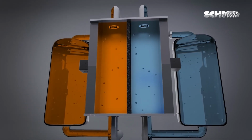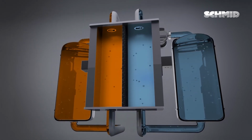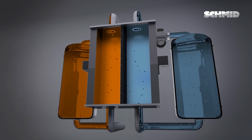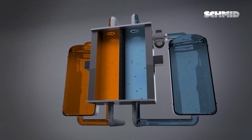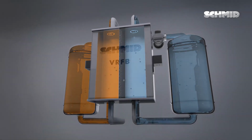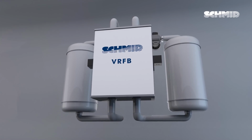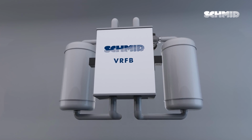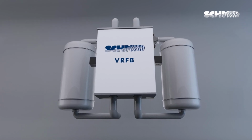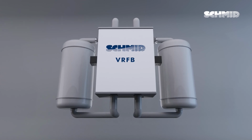Unlike other flow battery types, the all-vanadium redox flow battery incorporates vanadium in both electrolytes, eliminating battery deterioration through cross-contamination. The composition of the electrolytes, vanadium salts dissolved in dilute sulfuric acid, guarantees low hazard potential and best possible ecological properties. With all these benefits in combination with low production costs, the SCHMID VRFB is the appropriate means for renewable energy storage.